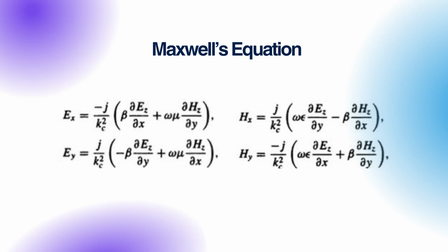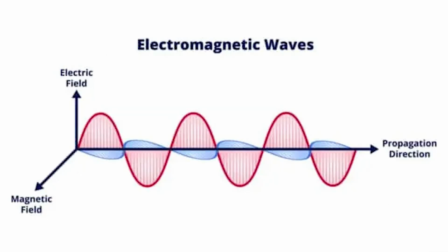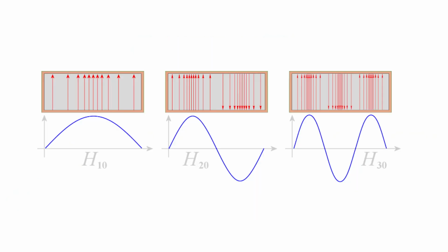Moving on, let's dive into the mathematical description of waveguides. The wave equation in a waveguide can be derived from Maxwell's equations, where by the separation of variables, we can solve the wave equation for different geometries such as rectangular or circular. For example, in a rectangular waveguide, we get solutions in the form of sinusoidal functions that satisfy the boundary conditions. And for the characteristic equation, these solutions lead to a characteristic equation that determines the allowed modes and their respective cutoff frequencies.